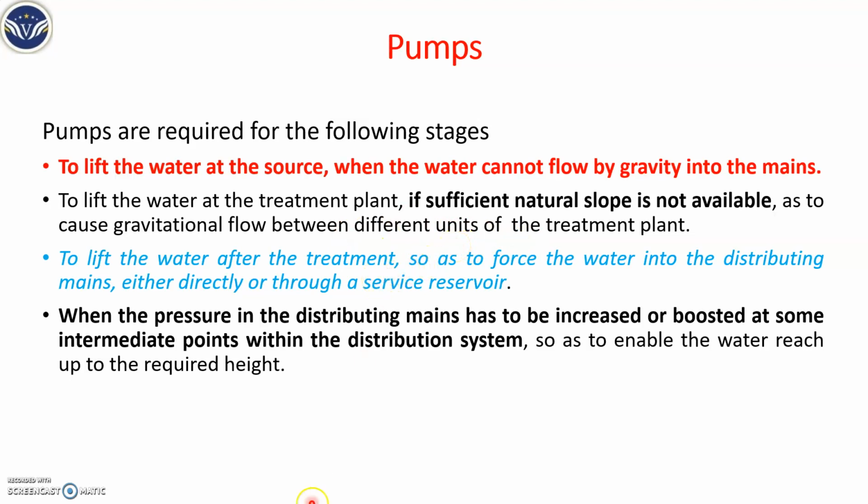Again, to supply water to a service reservoir: you can see in Nipani city itself there are many service reservoirs at a higher elevation. Your treatment plant, near Talab, is at a lower elevation, and you need to pump that water to a higher elevation. For that, the pump is required. Another one: if you don't have adequate pressure head in your distribution system, you need to boost it. So pumps are best suited for that.